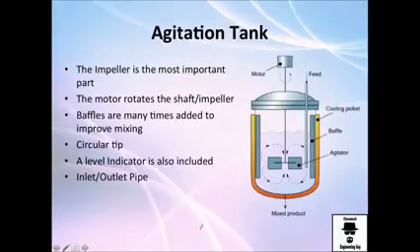Where do we do agitations? We normally do them in agitation tanks. What do we need? Well, of course the vessel and the impeller, which is here. If you don't have the impeller, you're not going to move any fluid. Also, you need a motor which is rotating and a shaft that connects the motor to these impellers